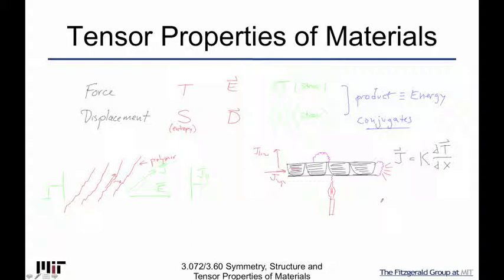So this is why tensors are actually not needed a lot of the times, is that we have situations either from sample geometry or from the fact that the crystals don't have really drastic property changes of different directions, that a lot of times you can reduce things to one-dimensional problems, either because it's like kind of these two extremes, either that it doesn't matter too much, and so you can kind of treat the thing as not having a high anisotropy in properties, or the opposite, where it's so high in anisotropy you only need to worry about one direction, for example.